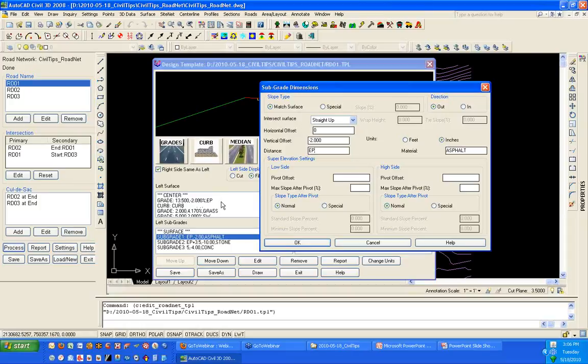The benefit of that means that if I have a turn lane or any kind of a widened or an adjusting edge of pavement that I define, as I set up a template point center line that has my edge of pavement following a different alignment, then the subgrade will automatically follow that edge of pavement defined here.